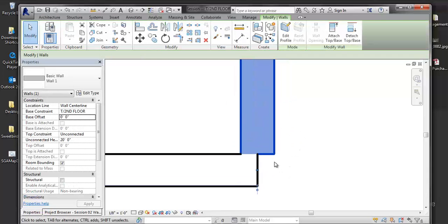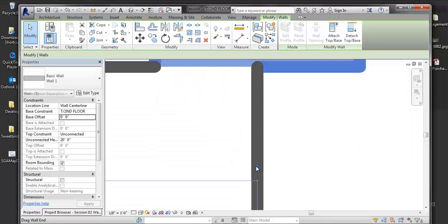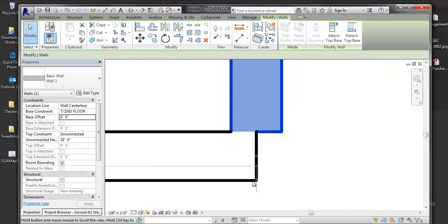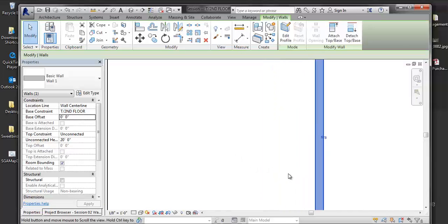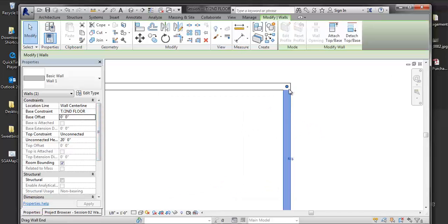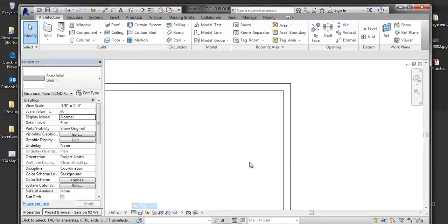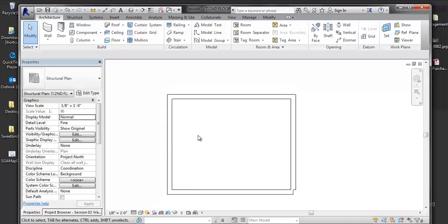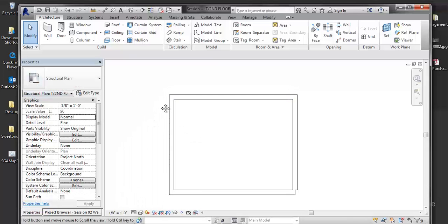And you'll see the joins can get complex. You'll see when Craig starts to open up the properties of the wall, you'll see the boundaries in terms of the layers of structure within the wall. And so it matches, there's a hierarchy of what it joins. So for example, if you look at a higher level detail, it wouldn't join a layer of drywall to a stud layer. Right? It would join the finished layer to the finished layer. Right. Structural layer to the structural layer. Cool. So yeah, I think that's kind of where we want to go now with it.